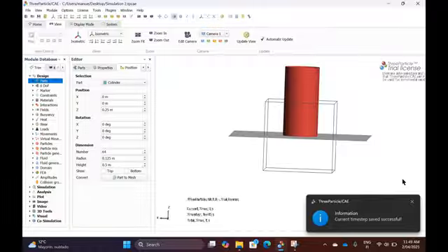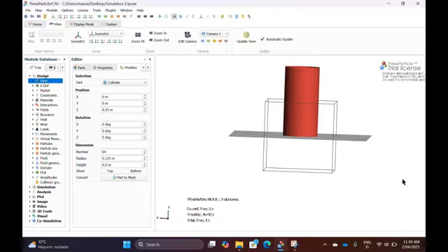That's a plane. You need to go to parts. Delete the cylinder because it's a plane. Delete. And select cylinder, yes, select it. And now call it cylinder or whatever. And now double click it and go to position. Now it should be there.